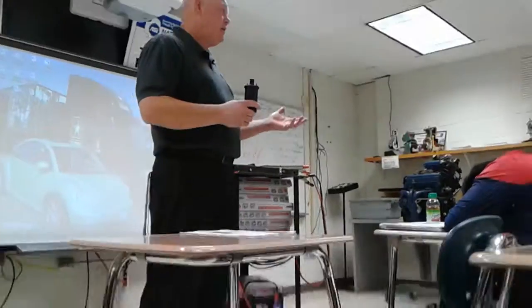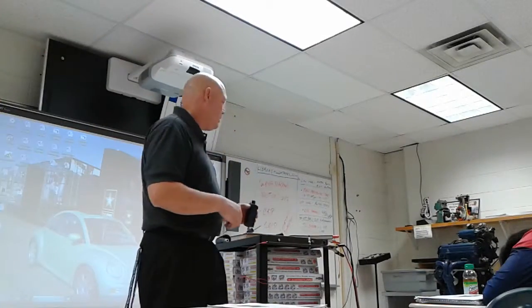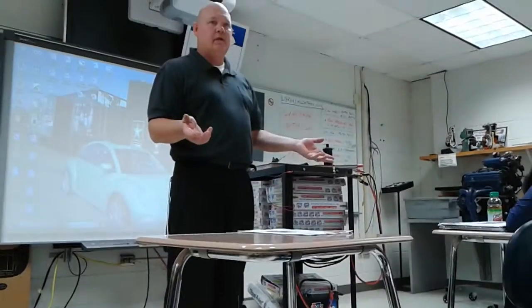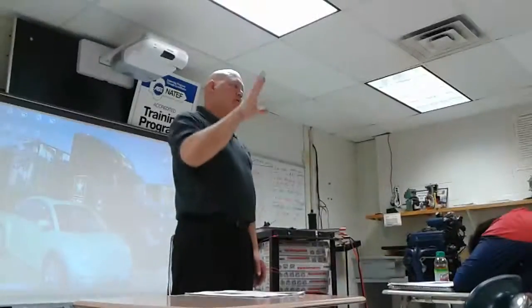So if you're not getting spark, in fact, on today's lawnmowers, they have gotten rid of the distributor and they've gotten rid of this, and it's transistors inside there. You guys are all familiar with transistors, right? You guys have got them on your phones. Everything is all transistorized these days. So transistors, the coil, when that magnet flies by that coil, you're energizing the magnets, you're creating electricity, and then the transistors are triggered to shut off and create the spark.